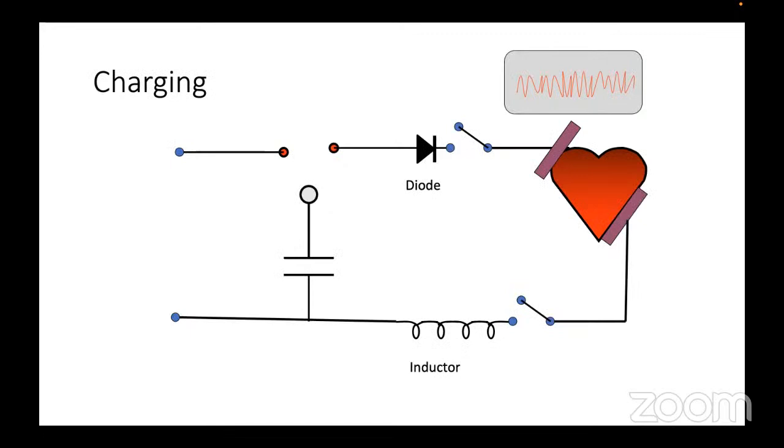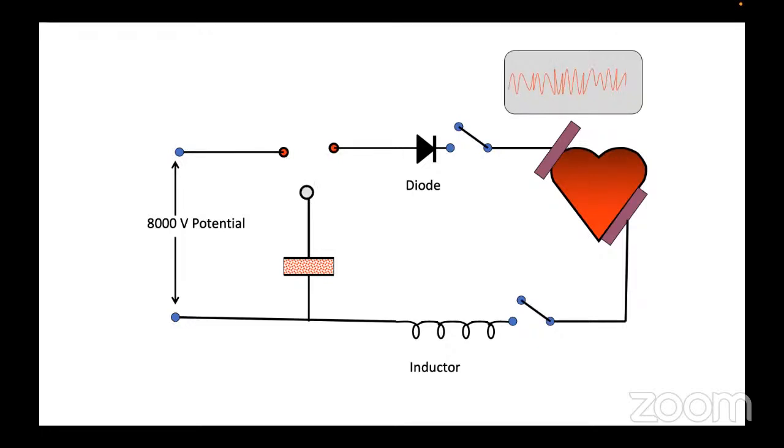So I've already talked about this circuit briefly. We'll go through this again because it's an important part of examinations. When you charge the defibrillator, the 230 volts or 240 volts which we have is stepped up to 8,000 volts. This charges the capacitor. And you apply the pad, and then it says, everybody stand away, disconnect the patient from oxygen. You go onto the charging circuit, you press the 2 buttons on the paddles. It doesn't happen nowadays. It's all attached to the patient. The pads are attached, but that's what used to happen.